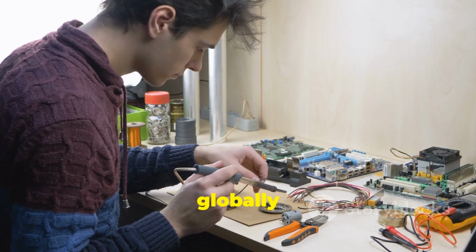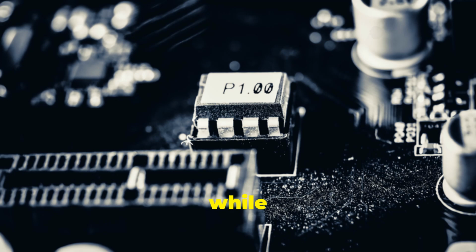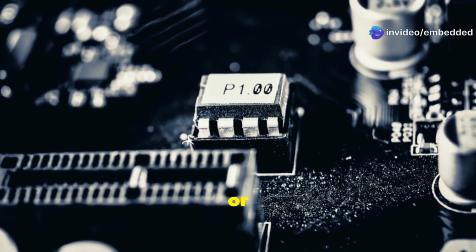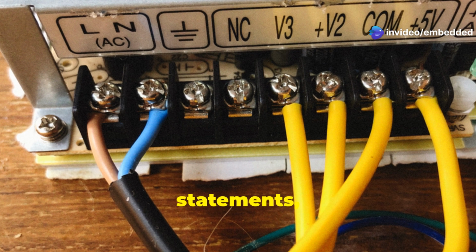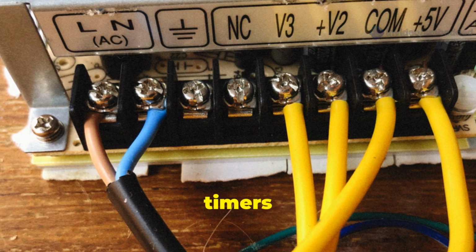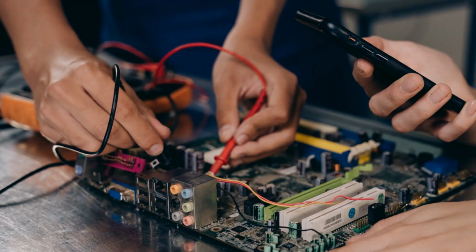Enable interrupts globally: __bis_SR_register(GIE). Main loop: while (1), sleep or do other low priority tasks. This example demonstrates how conditional statements, loops, interrupts, and timers work together to create a simple but functional embedded system.